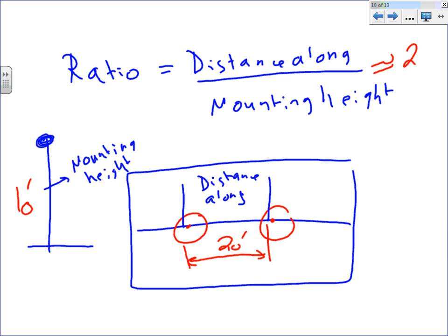But if you don't have software, a rule of thumb for mounting is 2 to 1, for the most part, without knowing anything about the fixture, the cutoff, the type of pole and all that. So if you want to throw out a number and make people believe you're intelligently educated in lighting, and they ask how you lay out your lights, just say 2 to 1.